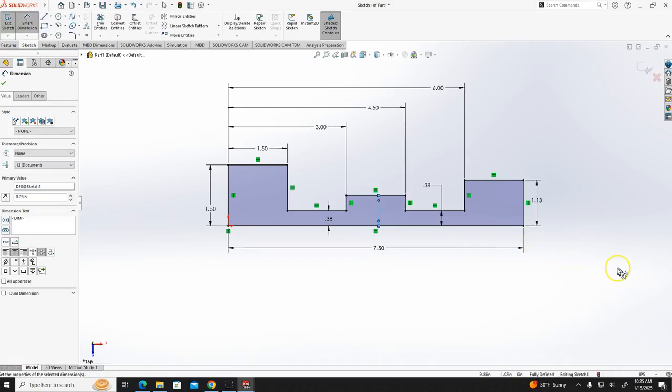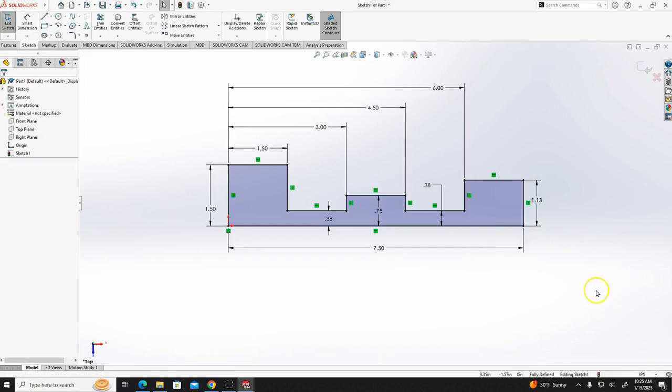So now you can see my whole sketch is black. It should also be a closed one, that means it should be shaded. Then and only then we can say this particular sketch is fully constrained, and it is a closed one. Any questions till now?